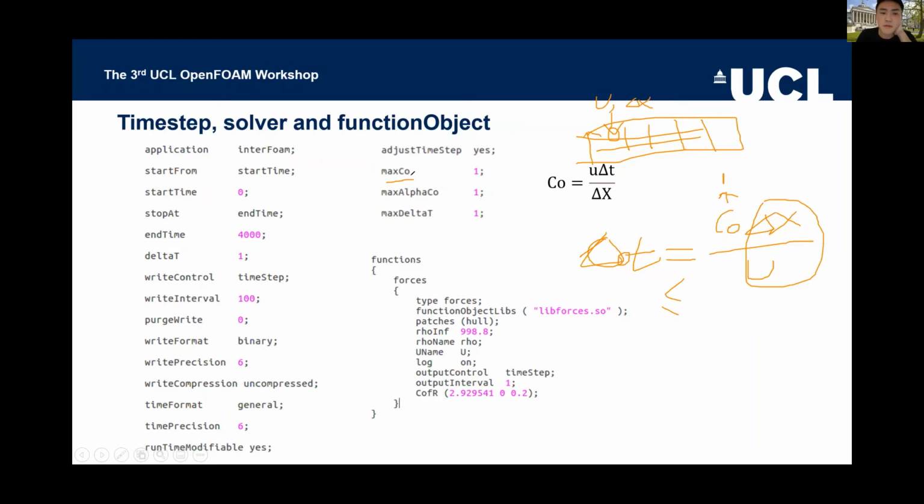As a normal practice, you may read online, a lot of places recommend setting this to be 1. However, from personal experience, in model scale this is recommended to be 1, but in full scale I usually can set this at 10 and it doesn't have a problem, though I cannot guarantee. I just tested by myself in full scale simulation.